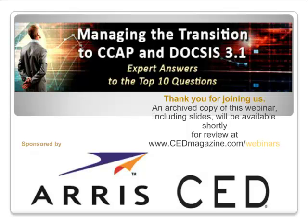Okay. And moving right along, this is question number 6. George, how do you see the revival of RFOG with DOCSIS 3.1? Could a wide upstream carrier, 48 MHz / 98 MHz, solve the OBI issue because then only one modem at a time would send data? Or do you expect new problems with the burst mode upstream due to the OFDM modulation?